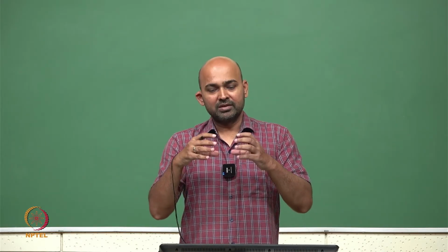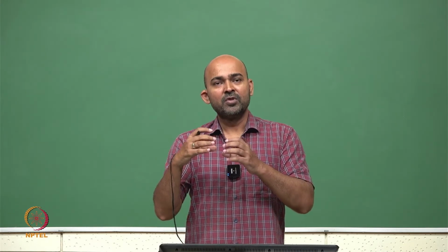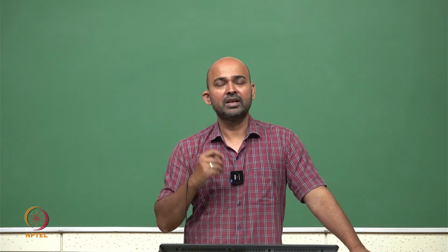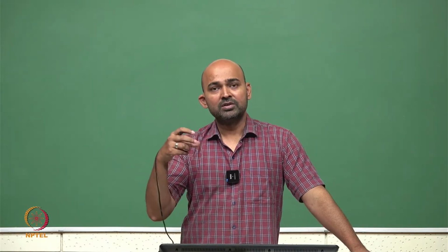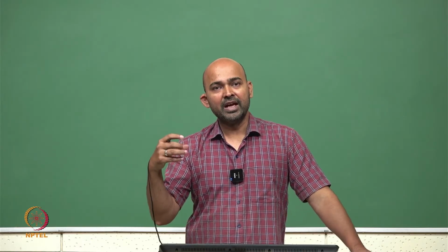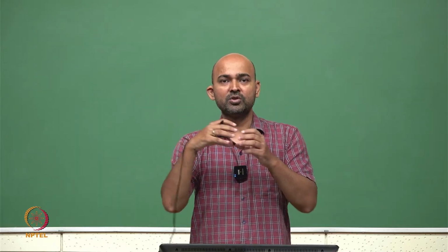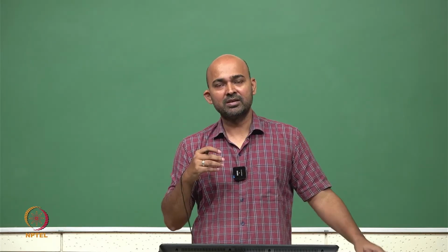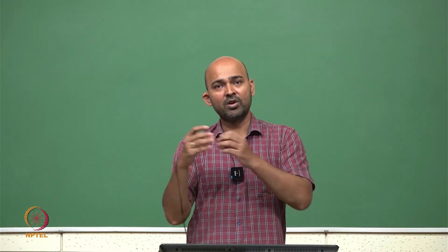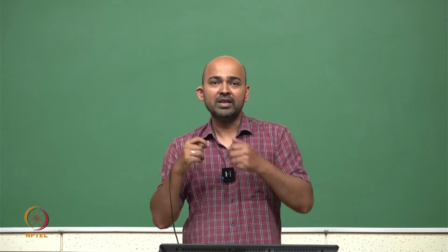So, all the connections we make in the RF PCB should be terminated at 50 ohm characteristic impedances. So, whatever load we have should be 50 ohm and should be matched to the 50 ohm characteristic transmission line, then the signal will not be reflected, it is perfectly matched.